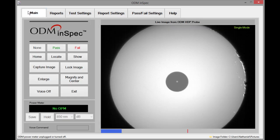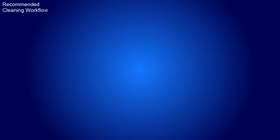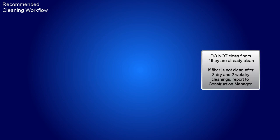On the main INSPEC screen, obtain a clear, focused image of the fiber end face to be tested. If there is visible debris in and around the core cladding area, clean the end face using your preferred method. Please note that fiber optic end faces should not be cleaned if they are already clean. The following flowchart illustrates the process for performing the recommended amount of cleanings for dirty fiber optic end faces.